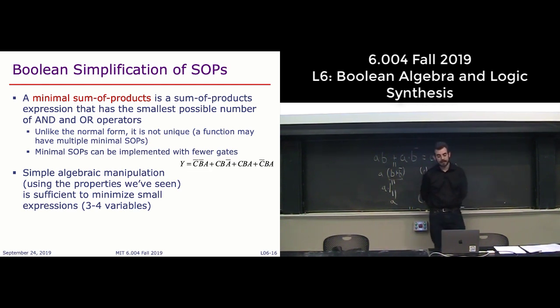So just as an example, let's take the expression that we had before and try to simplify it. And you can take a look at the different terms and say, well, the 2 terms in the middle here, I could reassociate terms, and it's CB, C and B, right? And then parentheses, not A or A, right? And so by reduction, that can be simplified.